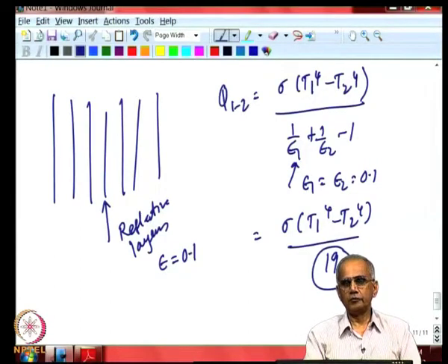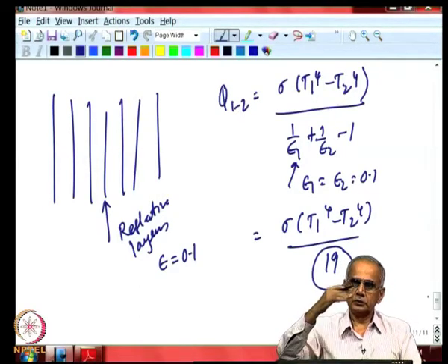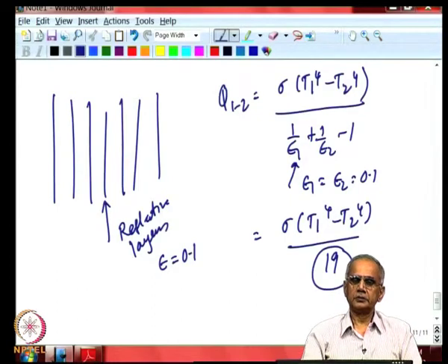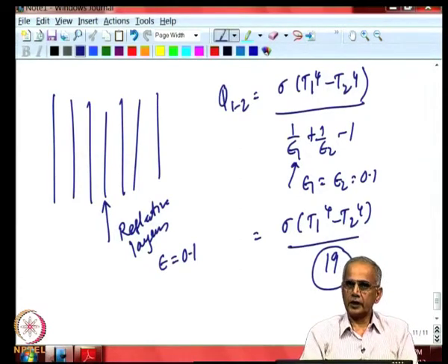So, this is now a very common application both in spacecraft as well as in other applications on the ground, where you cover a surface to be insulated with large thin parallel sheets of plastic coated with metal like aluminum, and this is a very inexpensive and very effective insulator you can have.